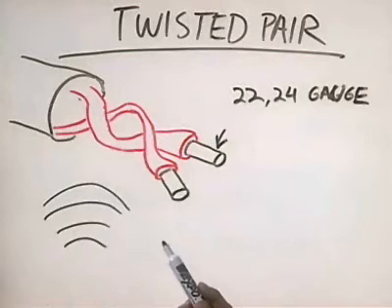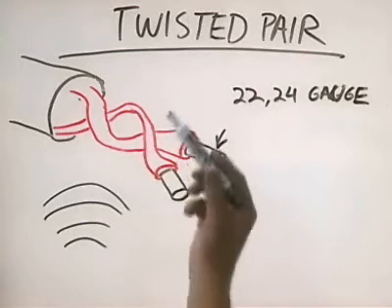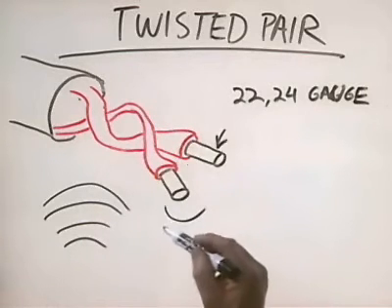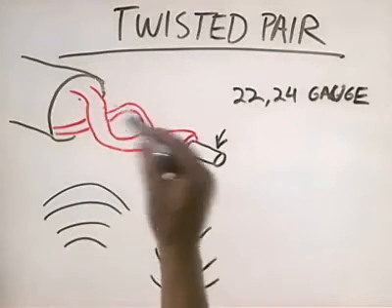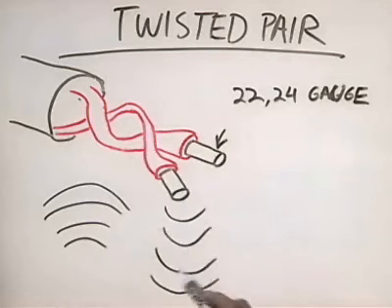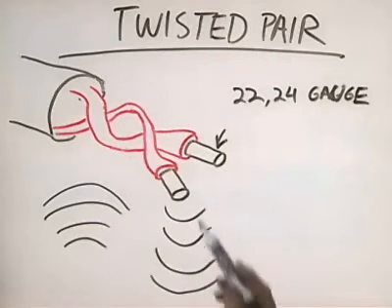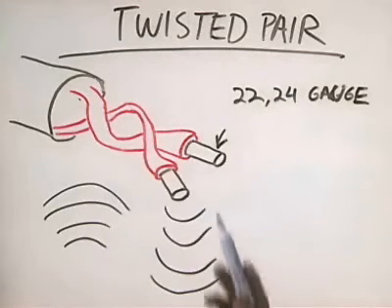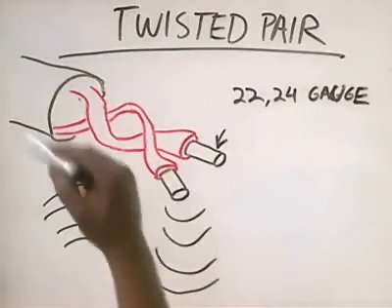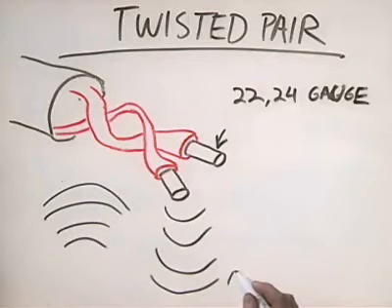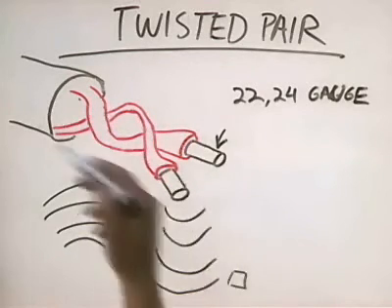because these wires will just pick it right up. They absorb signals really easy, but another one of their weaknesses is that they radiate signals. The signals running through the wire get kind of broadcasted very weakly, but they get broadcasted out through the wire itself. And that makes twisted pair cabling susceptible to eavesdropping. If you had someone with the right equipment, they could be outside of the cable and using a special type of radio receiver actually pick up the EMI coming off these wires and be able to capture the data that's coming off.